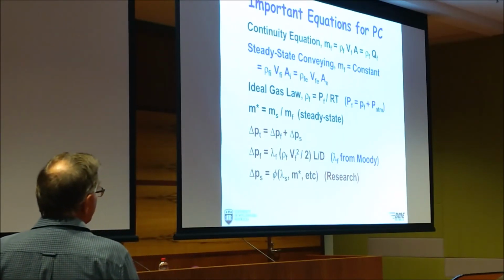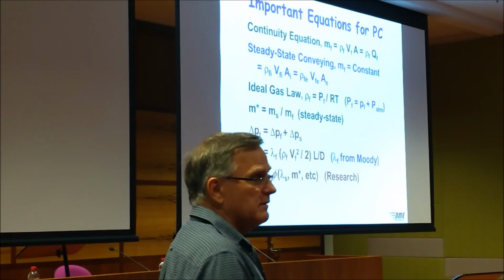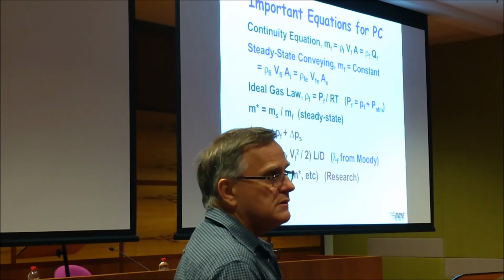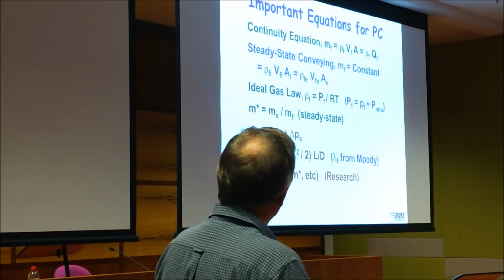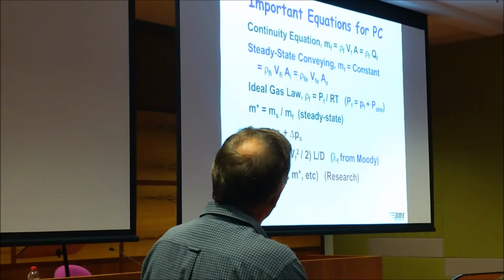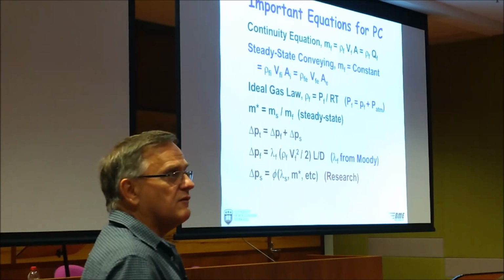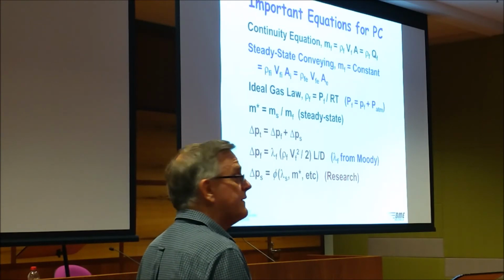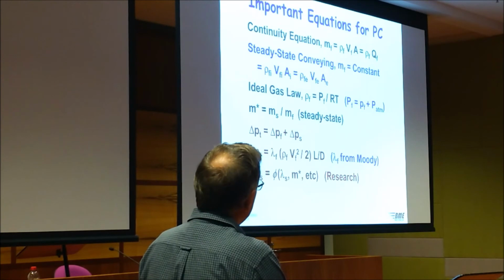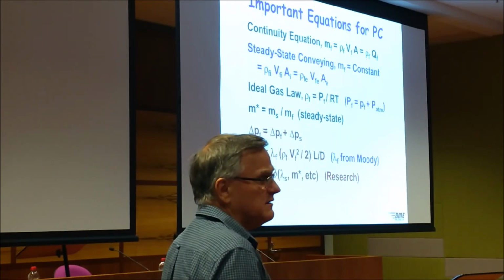Now, solids pressure drop. There are still people doing research around the world to come up with better models to predict solids pressure loss, and we're not going to do that here. So you can ignore that part of the equation if you like. It just says that it's a function of your solids friction factor coefficient, solids loading and all these other complicated factors. But this one we can use Moody and do some calculations. And for a dilute phase system we can do 90% of our design already.